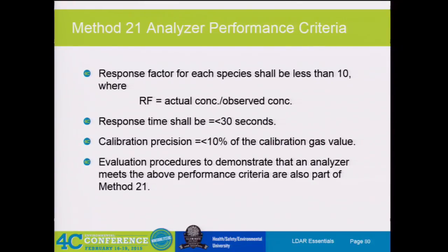but most folks have gone to a level of saying about 2.5. So when we audit, if we calibrate and we're doing everything, we try to get within 2.5% of the cal gas value, because we have the level of detail to get there. And if you actually look at it, if you calibrate within that accuracy at the beginning of the day, there's very little to no chance that you're ever going to go less than 10% and have to remonitor all of your results. So it's just a good idea to add that piece.